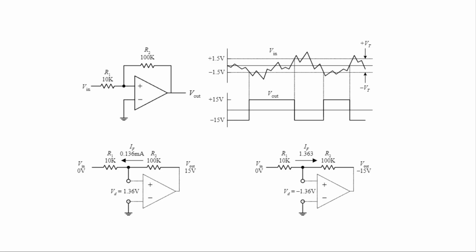Now, an important thing to notice about this equation is that the voltage fed back to the non-inverting input will act to drive the op amp harder in the direction the output is currently going. Recall that the negative feedback acted in the opposite way. The F of V out term subtracted from the expression, preventing it from maxing out. For most applications, it's desirable to control the gain, while it's undesirable to go to the extremes. There is, however, an important use for positive feedback when using an op amp to make a comparator.